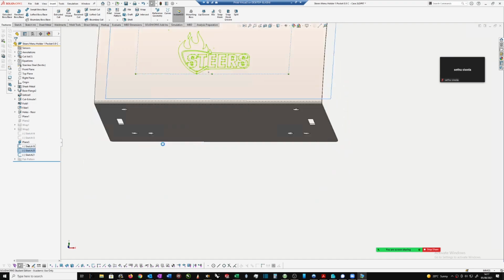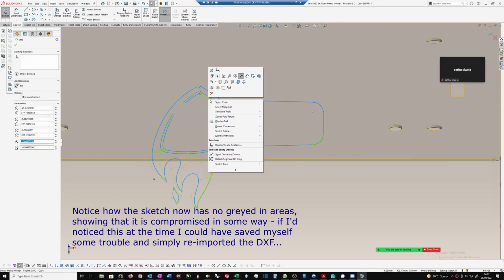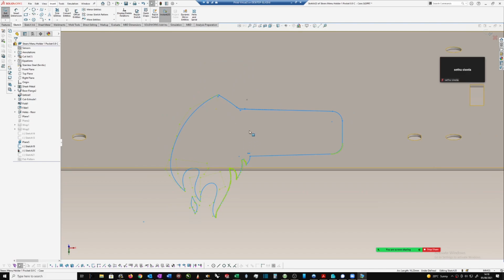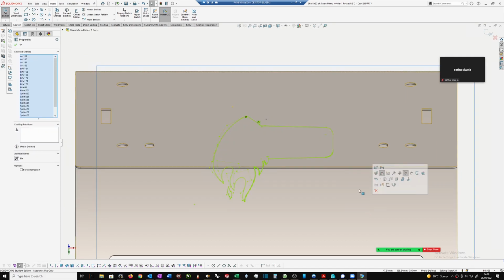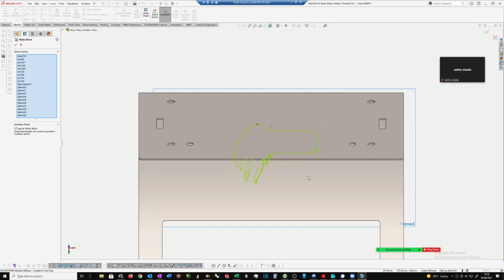Okay, so I want to go back into this bottom sketch, and now that I've made use of all of these parts, yes, I can window select and delete, and then I can just select chain, delete. Okay, so these are splines, and that's all I want in this one. And I now want to make this as well into a block, so I'm going to window select it, and then select the block tool, go back to the insertion tool, layout, and then that little blue